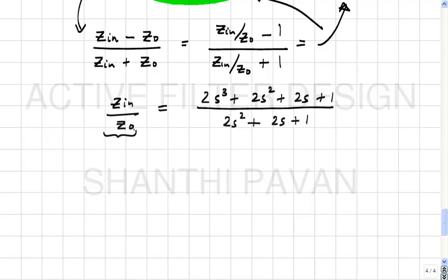From the power that needs to go into the LC network, we find the reflection coefficient looking in. The reflection coefficient is a measure of the deviation between the input impedance of the LC network terminated in the resistor Z0 and Z0 itself, right? Which means that we can find Zn as a function of s. Given Zn as a function of s, we presumably can find the network given its form. We already know it's a ladder. Correct?